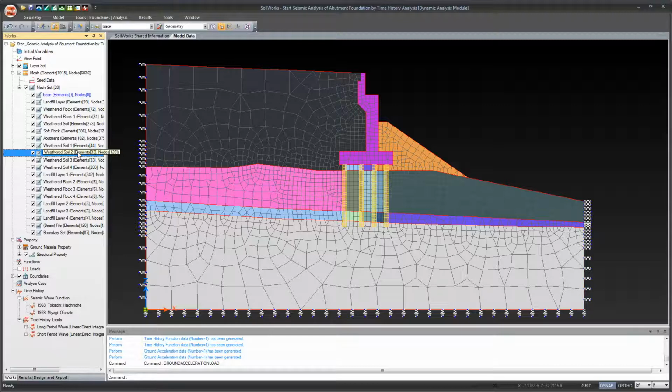If you have a model that's giving you some issues, it's always a good rule of thumb to go back and check over all of your elements, just to make sure that all of them are assigned, because that's where a lot of failed analyses or errors come up: you have something assigned but it's not actively in use.